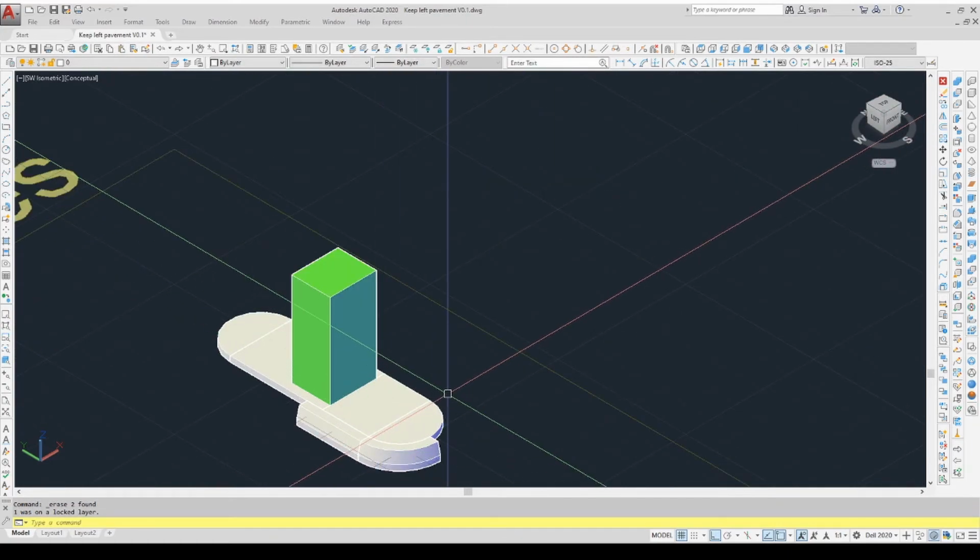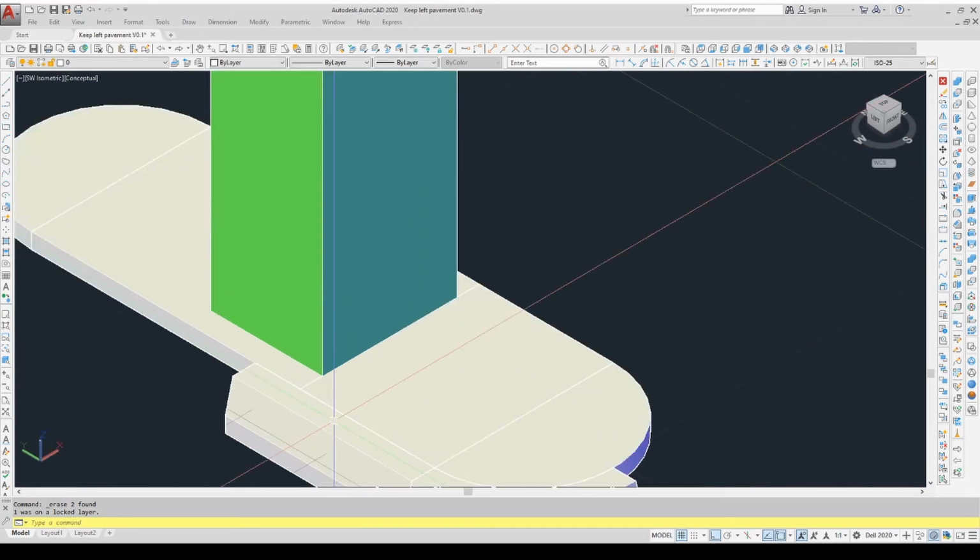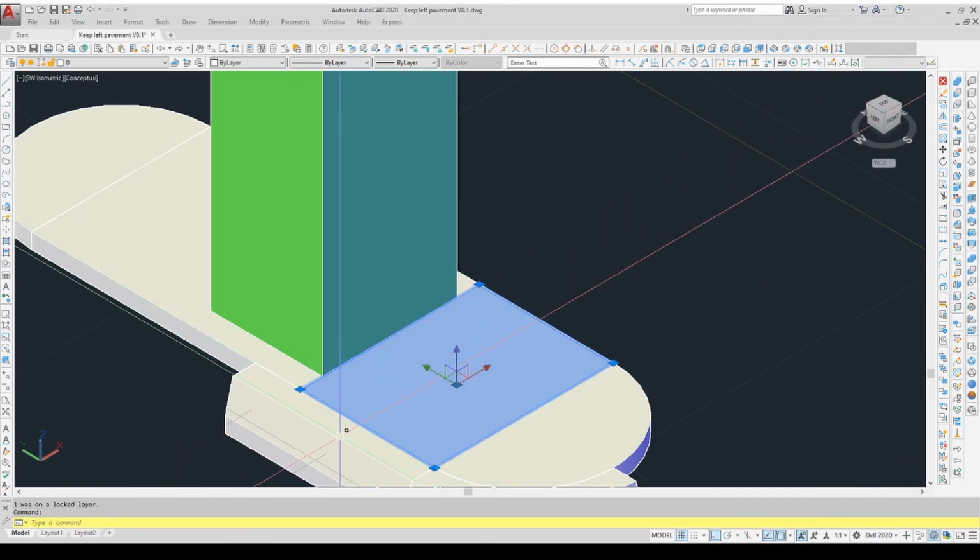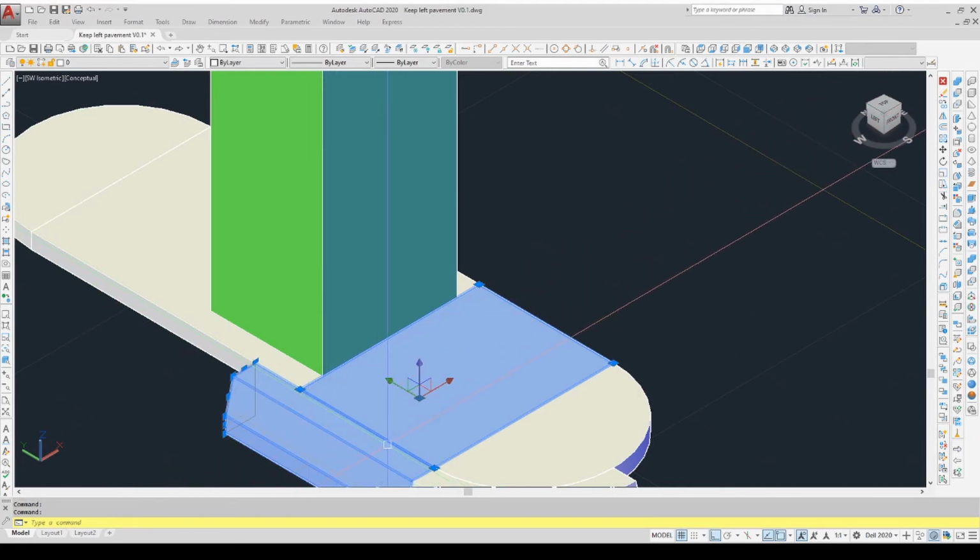So what do we want to do now? Well, a little bit of information is that CAD is deadly accurate. And the problem with this is that if I were to print it as it is now, the join between the curve and the pavement would simply disappear because it's infinitely small. In CAD's terms, it's 0, and therefore it's not going to print out. So we somehow need to show that, and this is where the artistic license of the designer comes into play. The bit that I'm kind of learning is that there would be a mortar line between them in the real world, and to signify that, we need to somehow put a bit of a trough between those 2 items to show it up as like the crack between the 2 items.